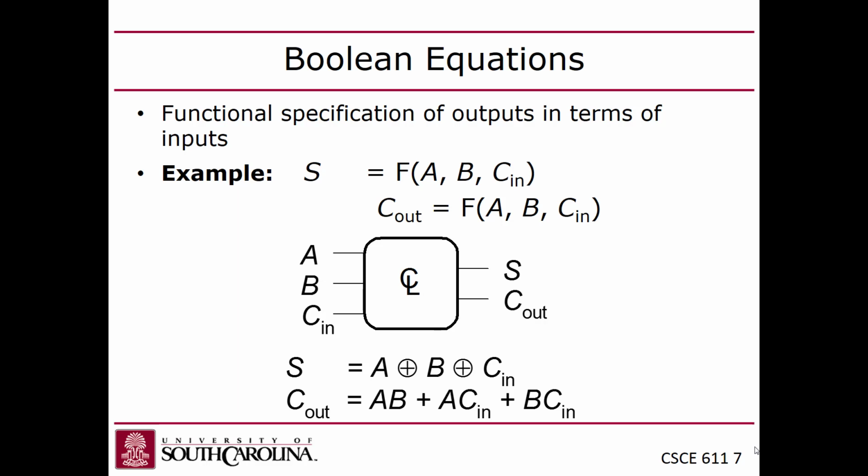Does that make sense? So if I put 1, 1, and 1, it's 3, and I can represent 3 in 2 bits. So the output would be 1, 1, right? In other words, a full adder is taking 3 inputs that are each treated as separate 1-bit values that I want to sum together into a 2-bit output. You guys with me? Okay.